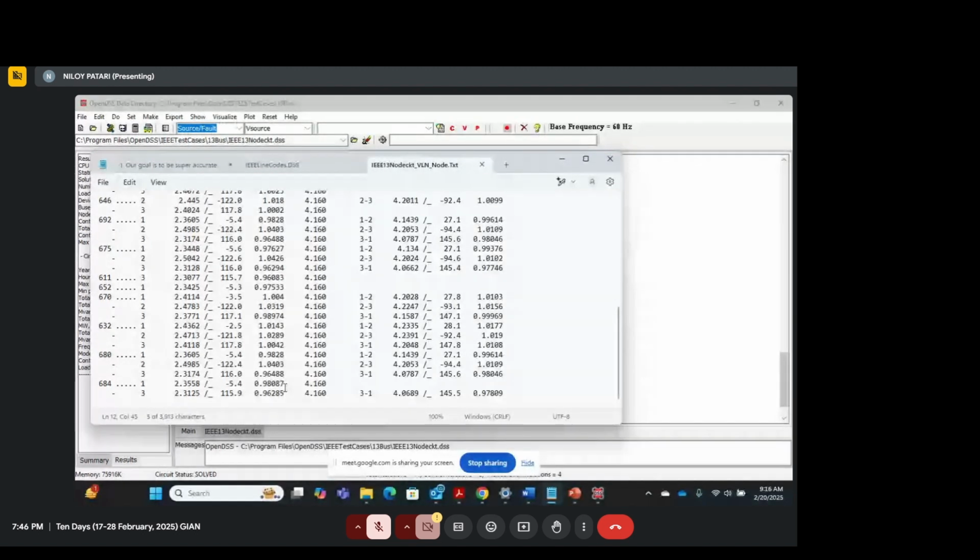So there is another standard, not like a standard, but a kind of rule that we follow in distribution systems: we try to keep bus voltages within plus minus 5% of the substation voltage. So we try to keep the bus voltages within that band of 0.95 per unit to 1.05 per unit. So this is in steady state. I'm talking about steady state.